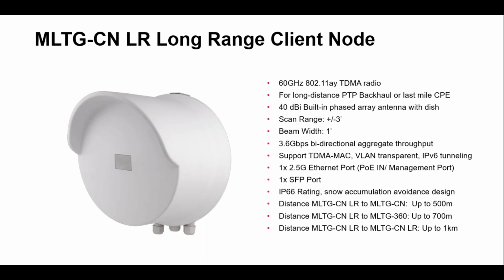1 degree is extremely difficult. It's extremely directional, where 3 degrees, or plus and minus 3 degrees, I should say, is going to be much more forgiving when it comes to alignment and getting the thing lined up, which is much better. And also it allows for some movement. So if you have a pole that's not, let's say, guy wired or something that can move a little bit, now it's more forgiving with a little bit of movement, where before it would be pretty limited or not forgiving.